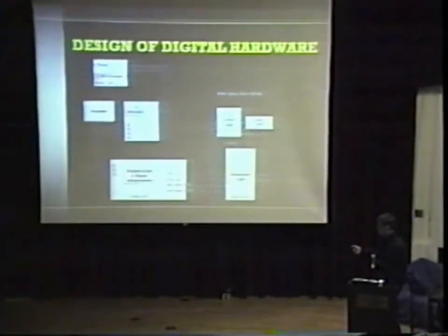As a synchronous system, the input to this system is constantly reading the column inputs for the rows, and it knows what row it's at based on the Q1, Q0 input here. The Q1, Q0 input, the 2 to 4 decoder, basically applies a ground to each row of the keypad intermittently at 50 Hertz.